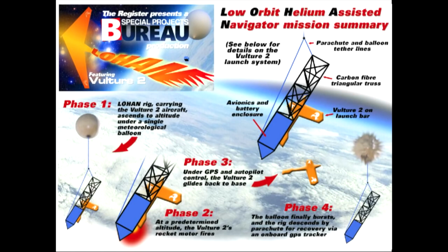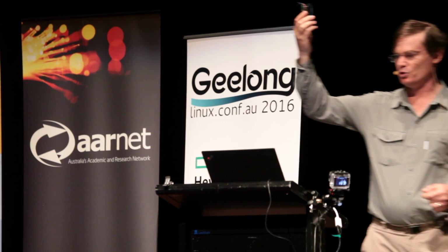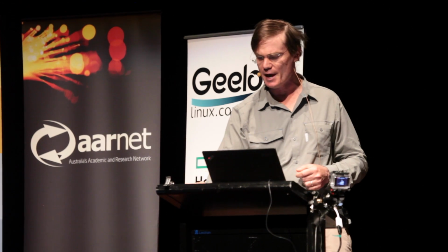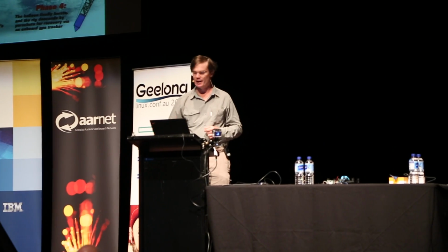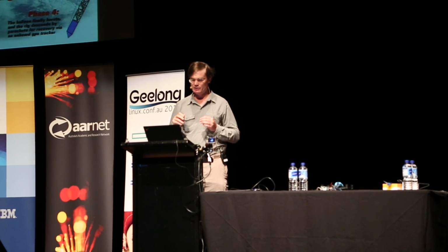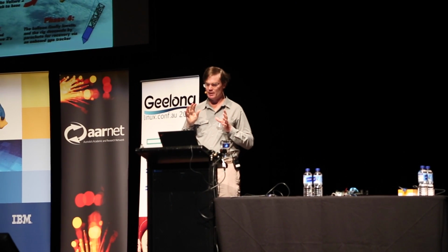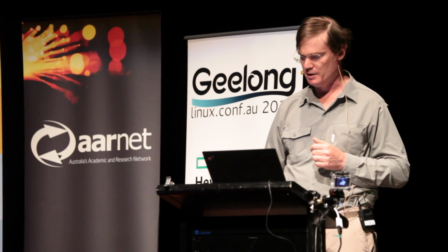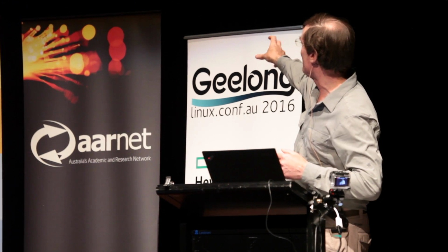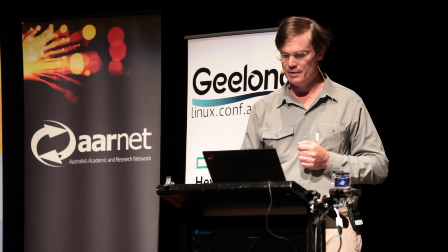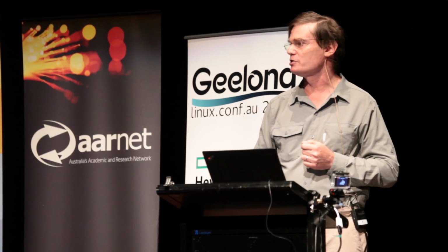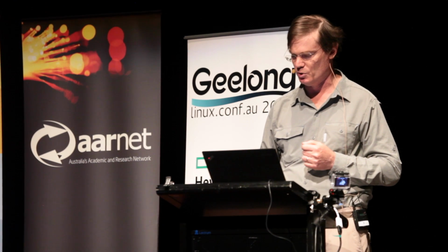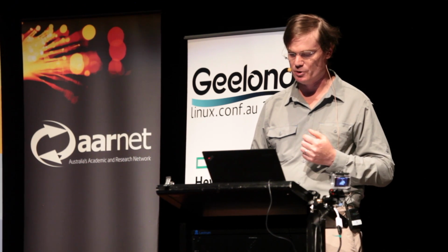It's got on board a little Raspberry Pi, right, running Raspbian, and it's got our little autopilot, one of these little Pixhawk autopilots running ArduPilot, and it's got a bunch of radio gear, again running firmware that we've developed. And when the balloon, so phase two begins when it fires off this rocket. So inside the tube part of the plane there is a rocket. And that rocket gives it about an 8-second burn time and accelerates the aircraft up to, they're hoping, around Mach 2.